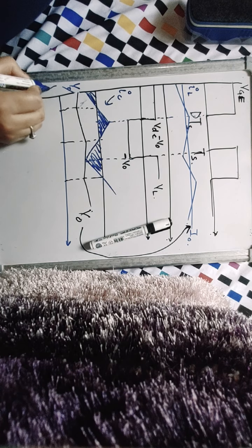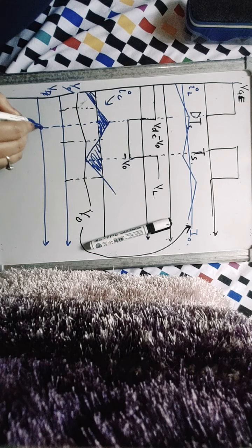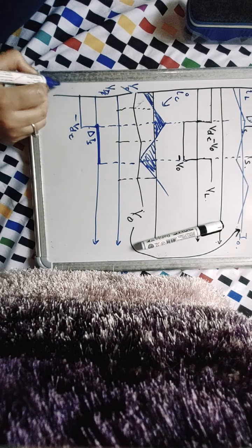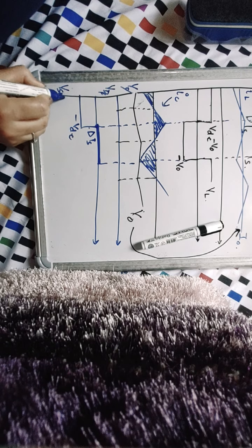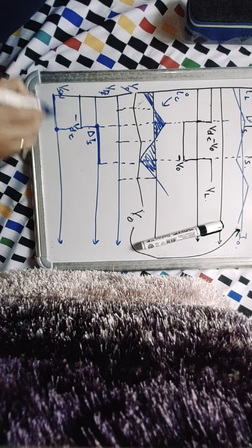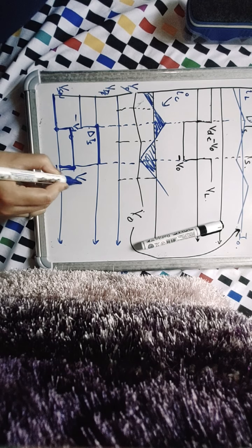Then we also have the diode. In the first interval 0 to DTS, the diode is blocking minus VDC, and then from DTS to TS it is conducting, so almost zero voltage. And if we draw the voltage across the switch, from 0 to DTS it is conducting, so it is 0, and from DTS to TS it is blocking plus VDC.